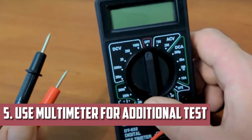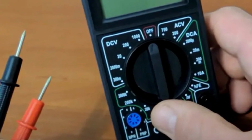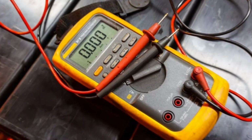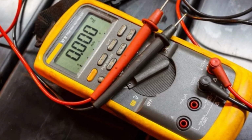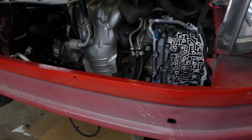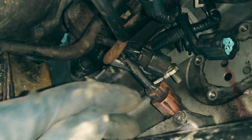You can perform additional tests if you have a digital multimeter. Start by looking in the service manual for the wiring diagram for your car. Connect the pins on the multimeter to the internal wiring of the transmission control module, and each side of the clutch solenoid circuit. To ensure the correct number of ohms, check each connection.